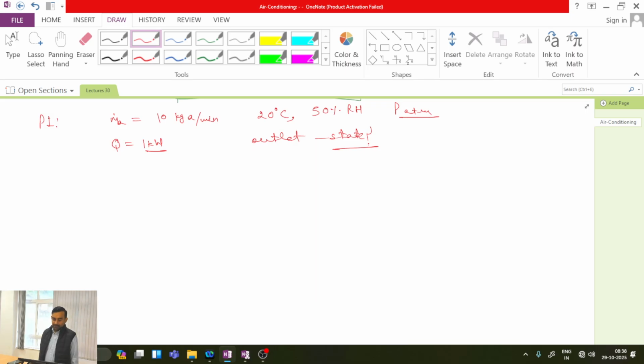And let me also tell you, you may ask me to give you a psychrometric chart, where you want to locate the state at 20 degrees Celsius and 50% RH and calculate the value of enthalpy or W. W means specific humidity. If I have a psychrometric chart, I can solve this problem with ease, but it can also be done without the chart using the relations which we have studied.